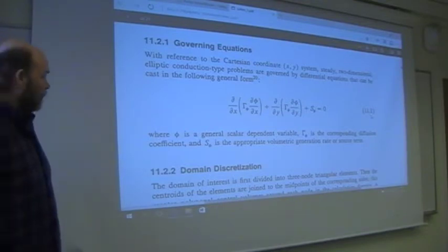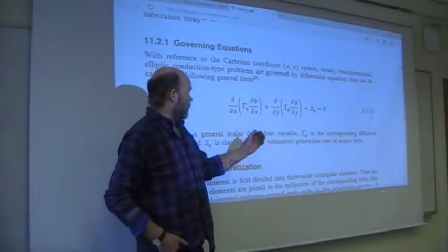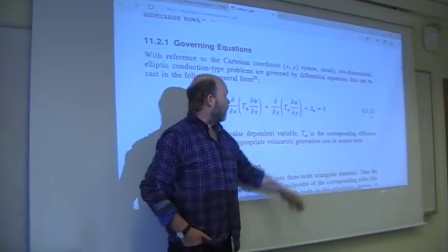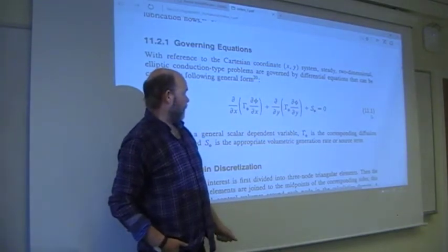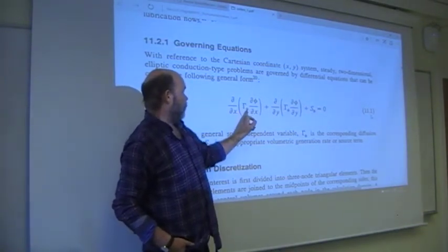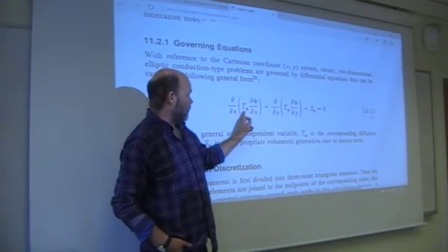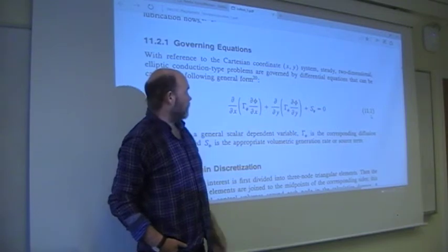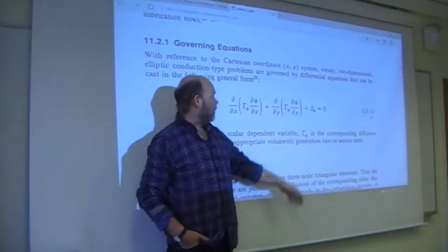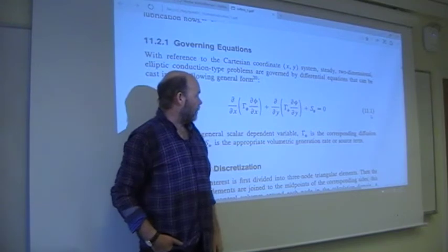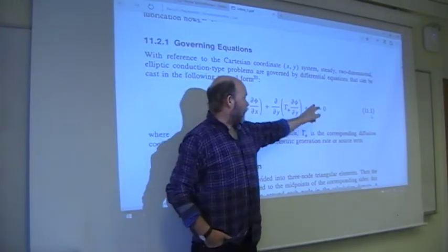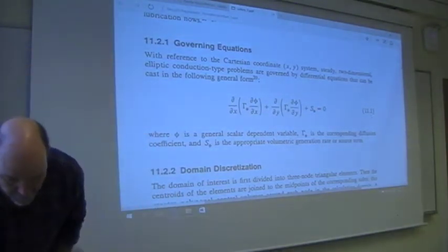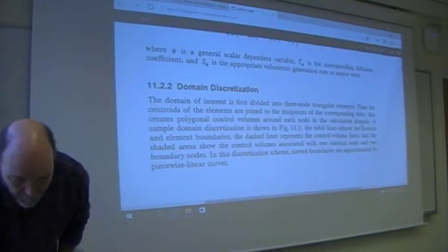And here again, the standard Patankar notation. You have a generic unknown phi. You have a generic transport coefficient, large gamma. If you think in terms of what we need in the end in Navier-Stokes, of course, phi will be a velocity and gamma then the viscosity. Here we may or may not have a source term, either constant or a function of the solution.